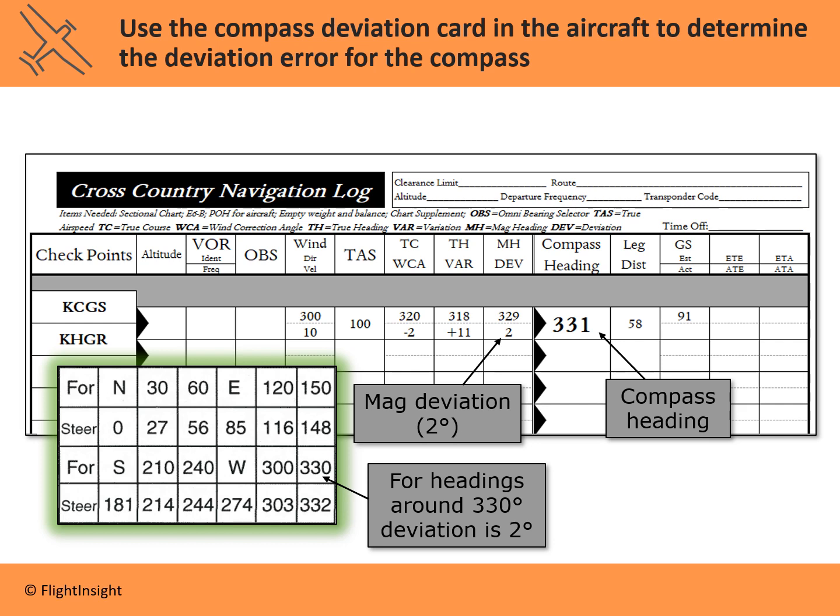The final step in this process is going to be to apply what's called the magnetic deviation to our magnetic heading in order to get our final compass heading. What deviation is, it's basically acknowledging that you've got the compass in the aircraft, which is just a little magnet that's pointing towards the magnetic north field of the Earth. But there's also other magnetic fields in the aircraft. You've got a lot of electronic communication and navigation on board. All those things throw off a little electromagnetic field. It's the reason why the compass is kind of dangling by itself away from the other instruments. It's to minimize the effect of those other magnetic fields on the working of the magnetic compass, but it is still going to be affected a little bit by that.